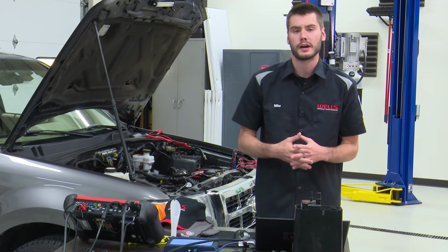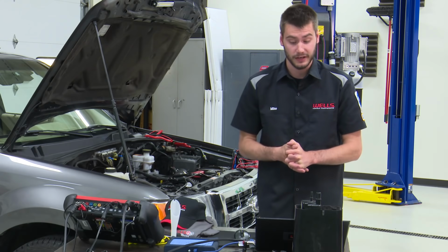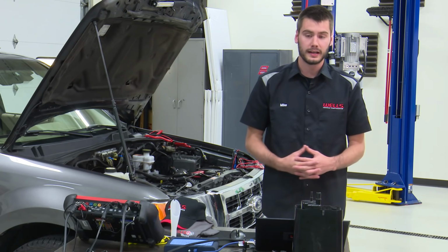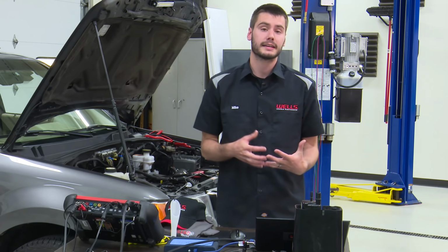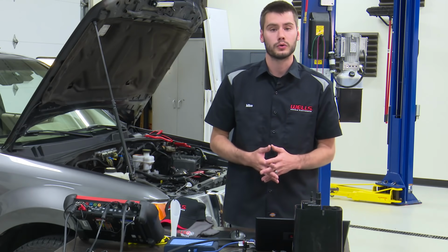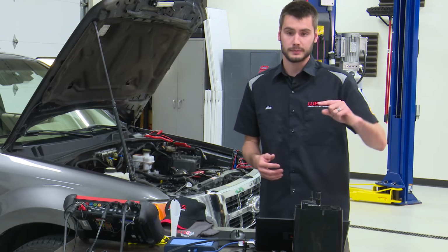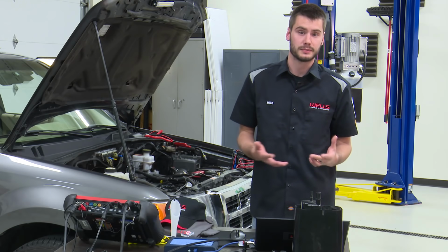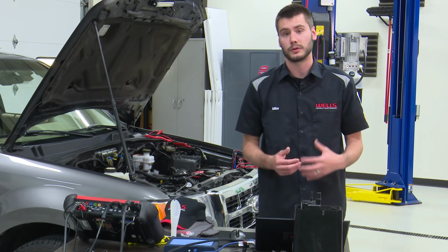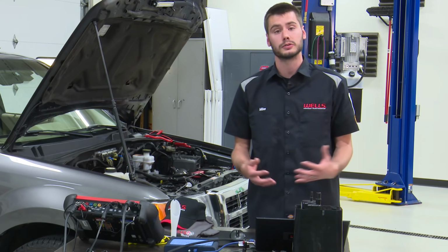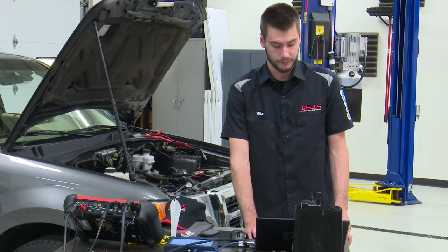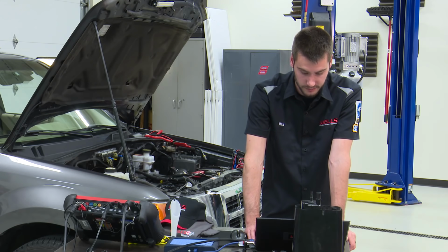They're definitely more rare. I know in my time as a tech, I've replaced very few fuel tank pressure sensors. I know when we get a lot of calls on the tech line, there's people asking about replacing the fuel tank pressure sensor, but it all comes down to understanding the code, and basically at that point they're reading down a list of potential causes and fuel tank pressure sensor happens to be on there. The sensor's job again is to monitor the pressure inside of the system or vacuum inside of the system. It's possible for it to be skewed or damaged, but it's also possible that something else is causing problems and that fuel tank pressure sensor isn't actually the root cause.